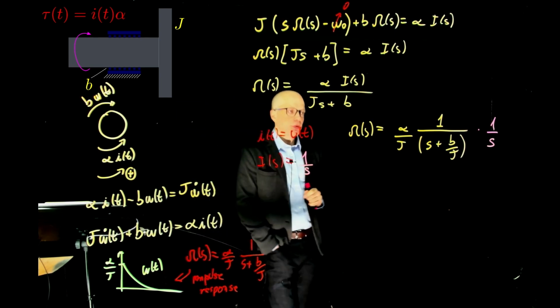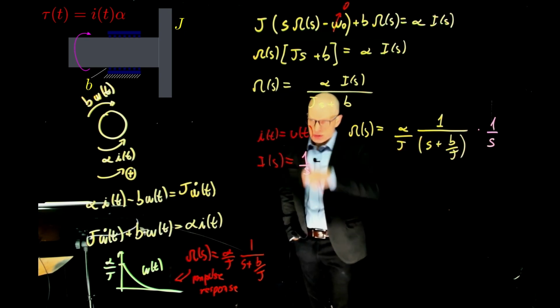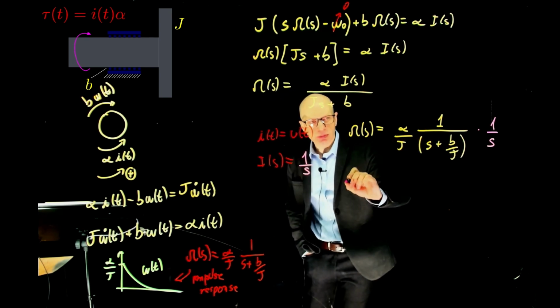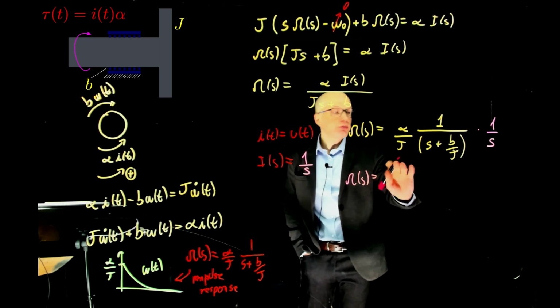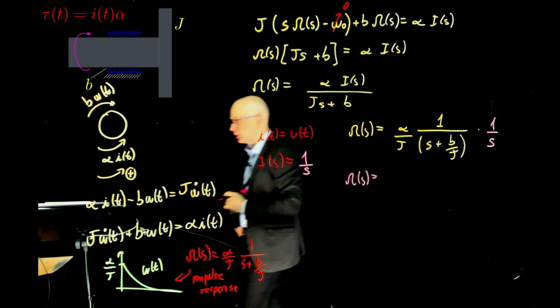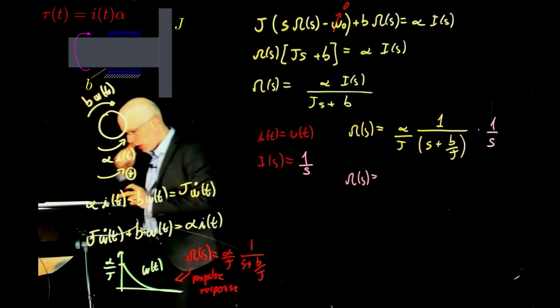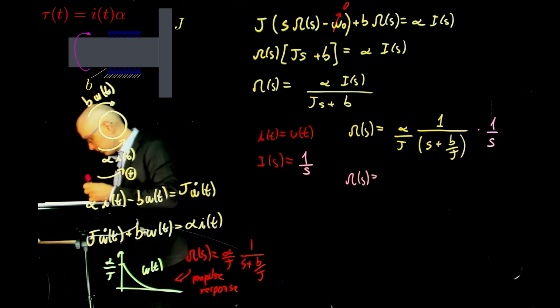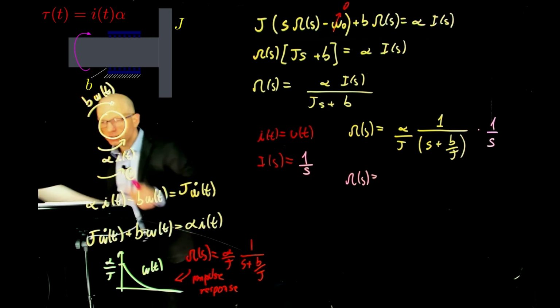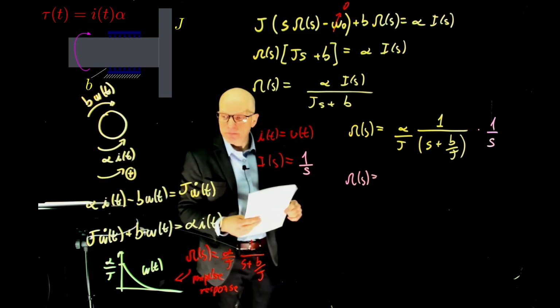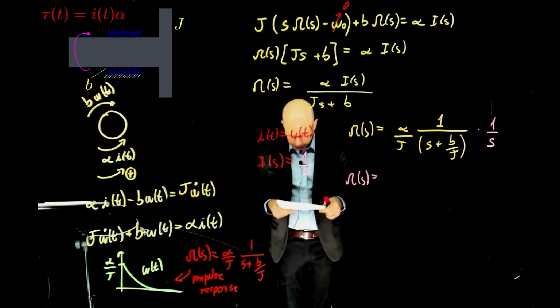Now, this is now the step response of the system. We can find the inverse Laplace. To do that, we'll need to find the partial fraction decomposition here. Should I do the partial fraction decomposition, or are we okay? That's a good exercise. We can try it there.